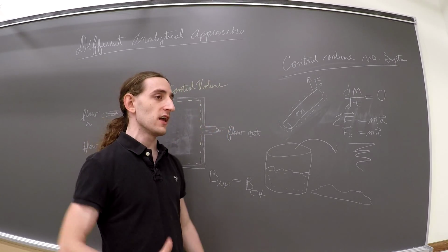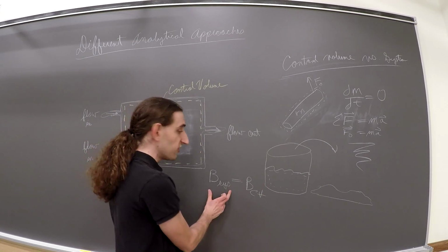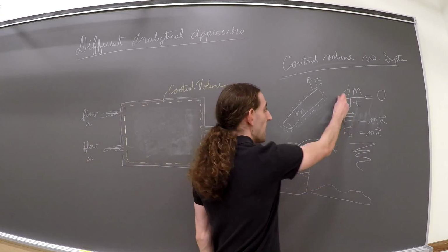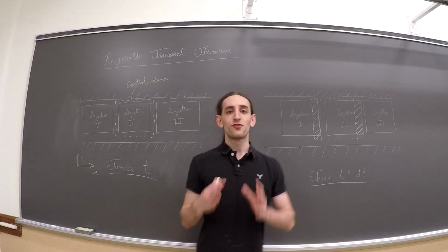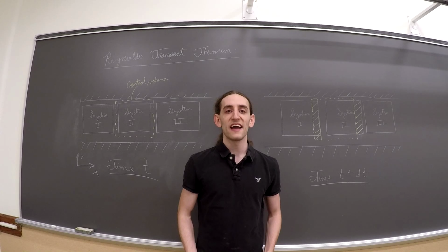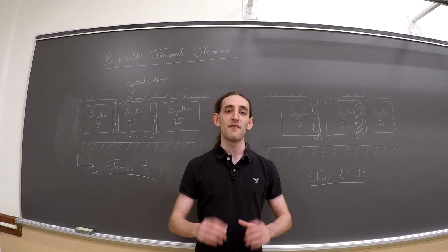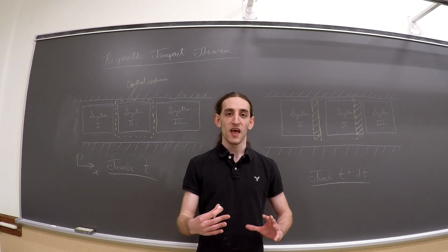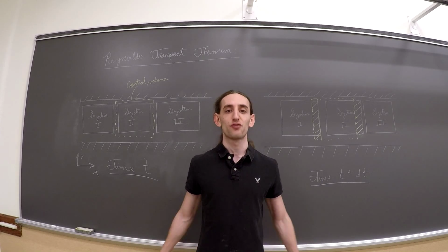We're going to try to formulate some kind of relation such that we can relate our control volume properties to our system properties, and that will allow us, in subsequent videos, to apply conservation of mass, conservation of momentum, and conservation of energy. So in order to relate the properties over the control volume to the system that we're analyzing, I'm going to consider this one-dimensional example and use that to derive the one-dimensional Reynolds Transport Theorem. Then I'm going to take those results and extrapolate in another video to a generalized result for the Reynolds Transport Theorem.